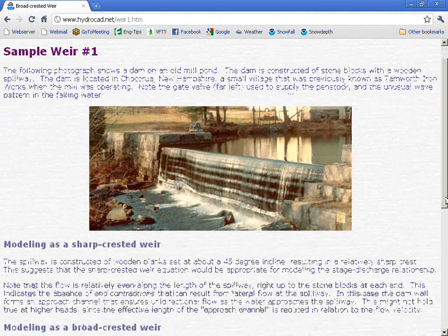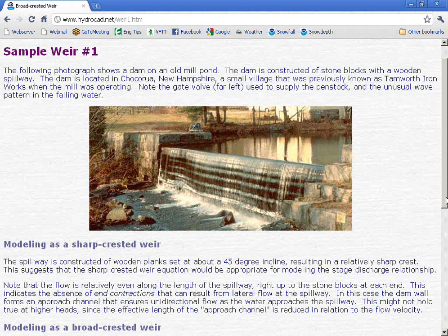is whether or not there's a significant variation in the weir coefficient that you feel you need to represent in the model. In many cases, you may find that those variations in the coefficient don't have a great effect on the final hydrograph routing. So I'd urge you to do a quick sensitivity analysis when you're looking at those situations in order to decide whether or not you need the additional complexity of a broad crested weir or whether you can just use a standard sharp crested weir, which also, by the way, gives you a broader range of geometry options, such as the V and the trapezoidal.